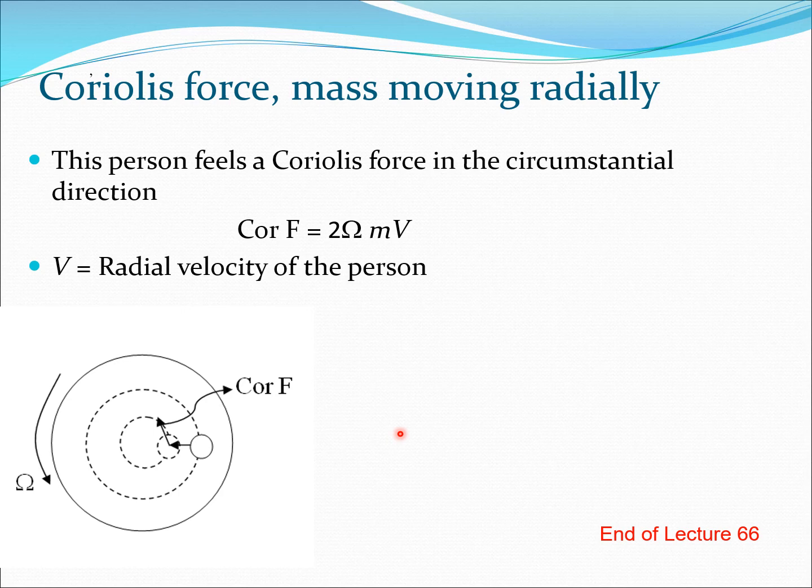Now what happens in the flap lag problem is you have similar situations. You have the rotor disk, and essentially the flap and the lag displacements cause certain motion to the masses which essentially create Coriolis forces, and these Coriolis forces are the root or the genesis of the nonlinear terms which are very important for helicopter dynamics motion. So I hope you understood today what is the genesis of the Coriolis forces. Remember, the Coriolis forces are given by twice into rotation speed into m into v.